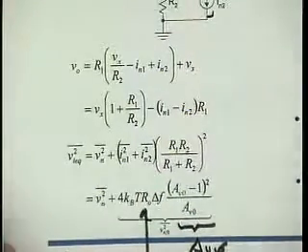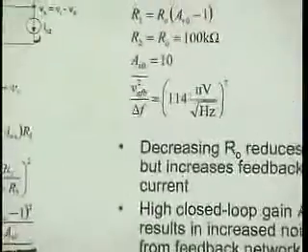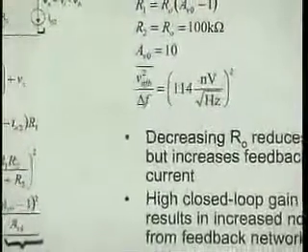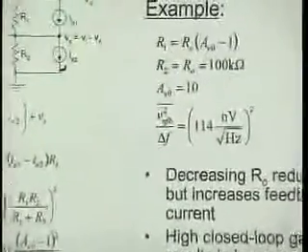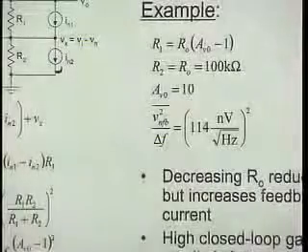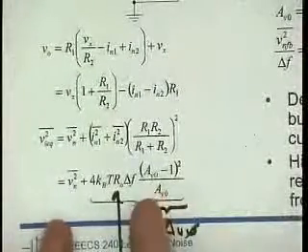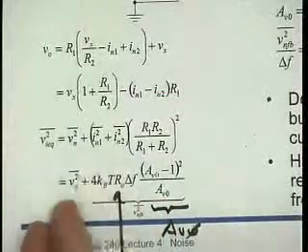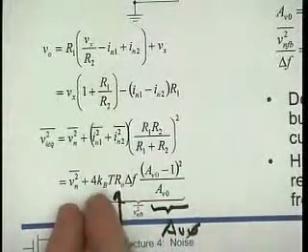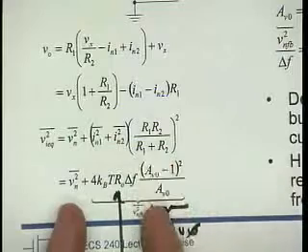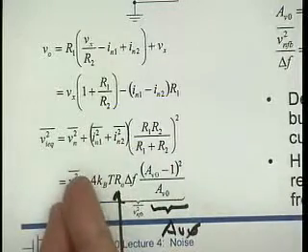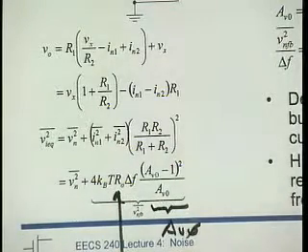Okay, and then I made an example here, kind of trivial. But the point is of course that now I really get extra noise from the feedback networks. I guess presumably what I normally will want to do is make this term here, the noise from my feedback network, small compared to this noise here, the noise from my amplifier. That way the feedback doesn't cost me noise-wise, right?